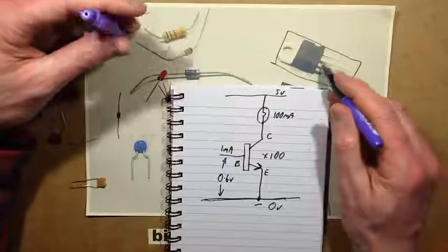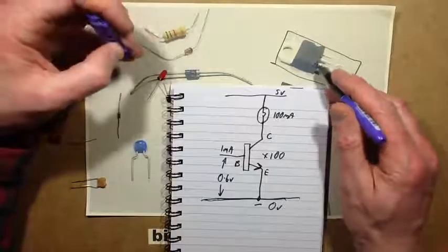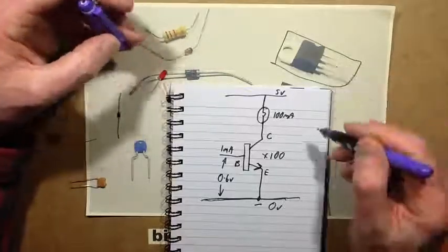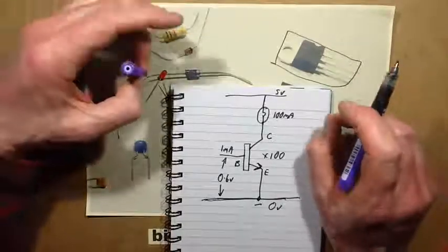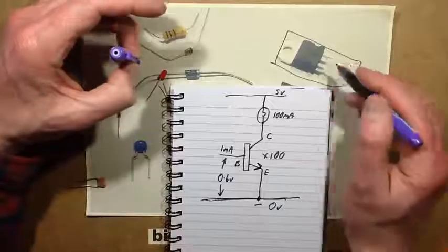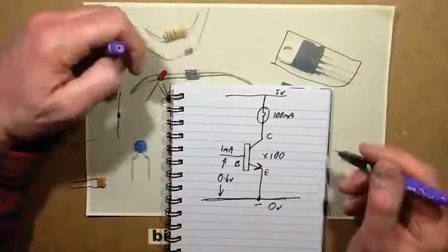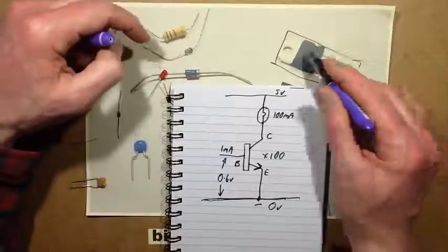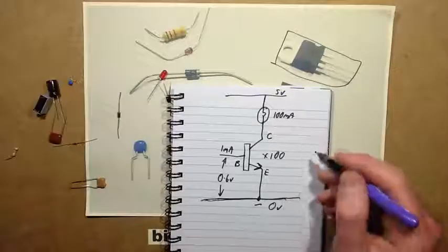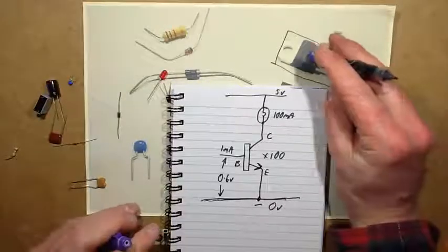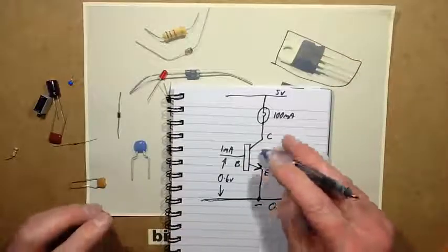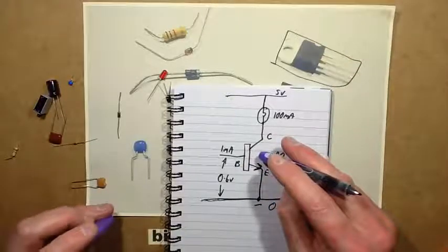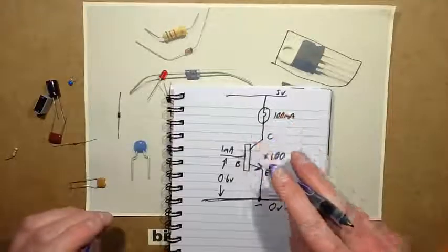They also have an extremely sensitive input, but they generally require a much higher voltage on their gate, as they call it, to actually turn on. But the current flow required to turn these on is virtually zero. It's a sort of capacitive effect. They're quite amazing things. You also get a hybrid. MOSFETs are not as robust as the traditional, let's see, bipolar transistor like this one.